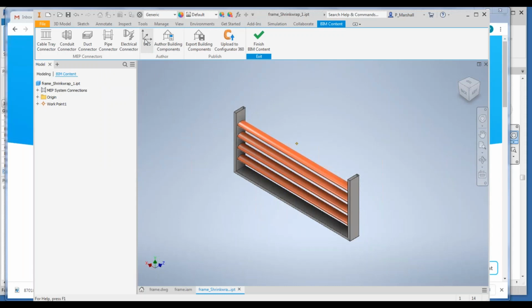We also can control the coordinate system that we're using. So here I want to have a coordinate system on that point that I mentioned before, with the x-axis along that direction and the y-axis along that direction. Remembering that in Revit, Z is up, we want to make sure that the sunscreen is oriented in the correct direction.